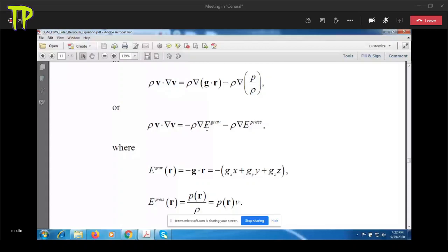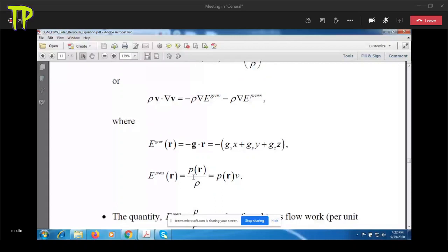So, sir, the formalism of the energy approach is not applicable to such cases. You cannot call it pressure energy. It is misleading to talk about pressure energy. And anyway, this potential energy is not p, it is p upon rho. So in such scenarios, we cannot even talk about energy conservation.